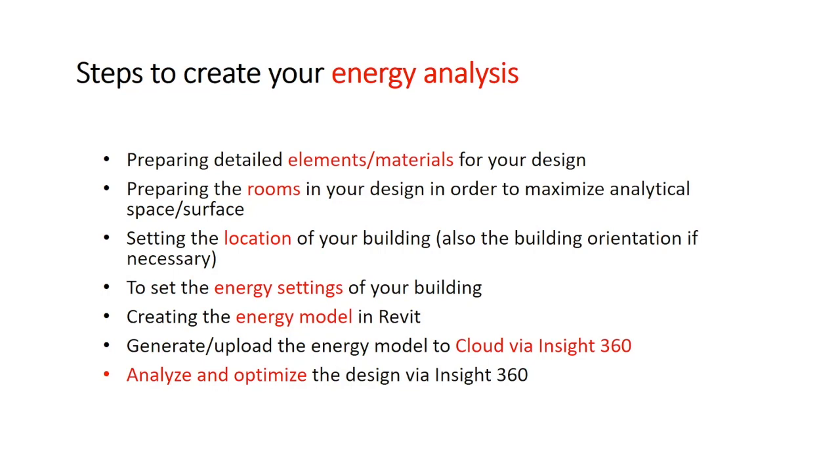You need to ensure that all of the spaces in your room can be assigned with this room, okay? As well as you need to set the volume of each of the spaces in order to maximize the analytical space and surface for your energy analysis. Thirdly, you need to set the location of your building.